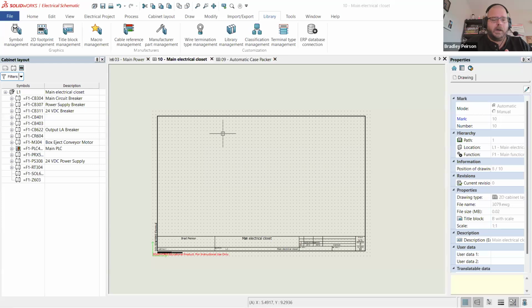They also by default come in two colors, standard ANSI, and then this is the ISO standard. It's a little lighter gray if you're working in ISO. Typically a 24 by 24 is my go-to for a generic cabinet. You can fit an awful lot of machine in a 24 by 24 cabinet, and probably 8 inches deep. So I'm going through and grabbing it. You can download a full CAD package, which is what I'm here for. That's literally why I opened their website. I need the CAD package. I'm going to open it and extract.